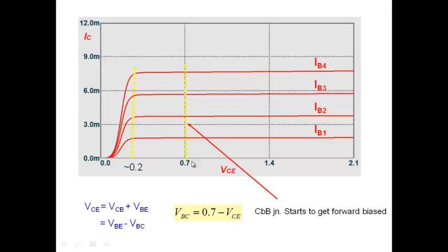But we know that, even though strictly speaking it is not forward active, maybe I can go as far as this, and still it's acting as if it is in forward active mode. So if you really want to push the boundary, you may say, well, to ensure that my transistor is effectively acting as if it's in forward active mode, I can maybe push my VCE as close as maybe 0.2. I mean, these numbers vary. Somebody may say 0.25 or whatever.